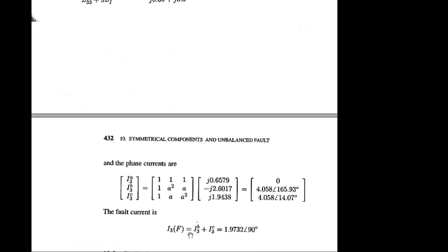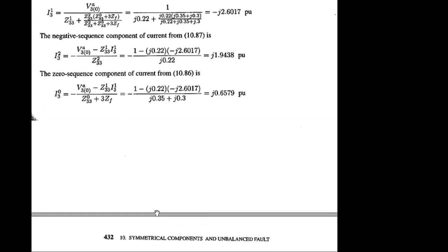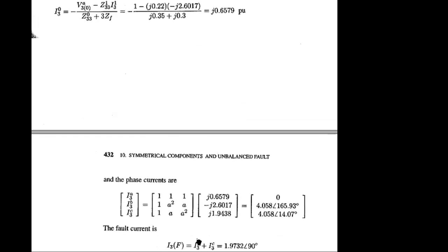For double line to ground fault, you have to make addition after the calculation. That means when you complete that calculation, you have to use these two pieces of information to get the final fault current, which is only for double line to ground fault. Remember that for double line to ground fault, after solution, you have to use the final outcome, this one.